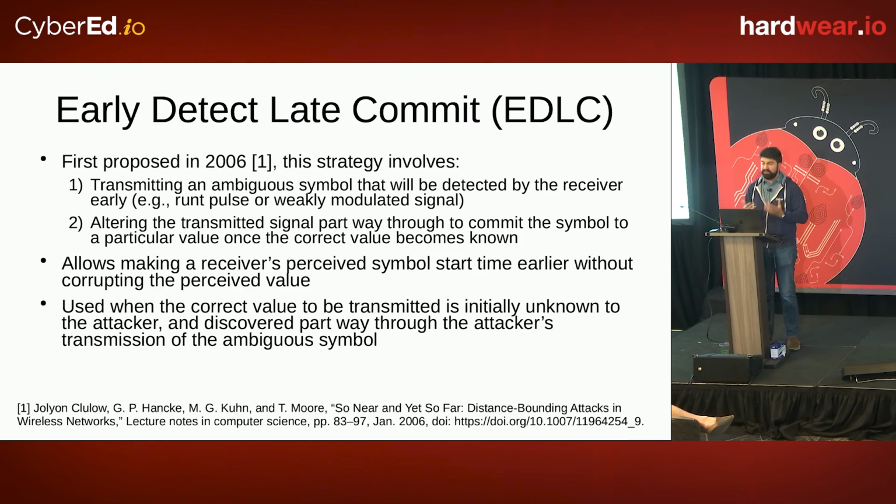Now, there are more sophisticated attacks that can be used to tamper with the perceived packet receipt time. One of the most notable is something called the early detect, late commit attack. And the idea with it is that you start, as an attacker, sending a response early even though you don't know what the correct bits should be. And you send a predictable preamble early,